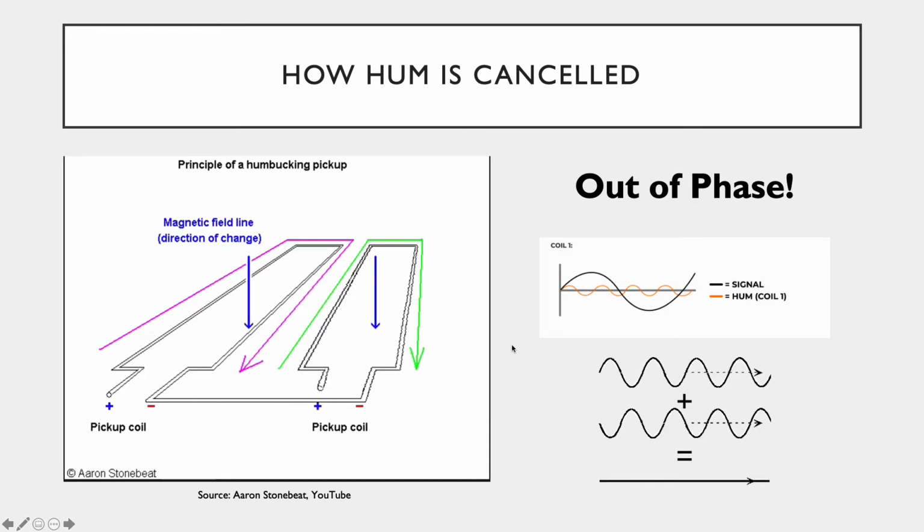So let's think about what we can do to change the direction of the electricity over here. If you remember, the direction of this current is dependent on the direction of the magnetic field line. If we think back to the right-hand rule and how Lenz's law states that the induced current's direction will always oppose the change of the flux, we also have to remember that there is an oscillation going on.